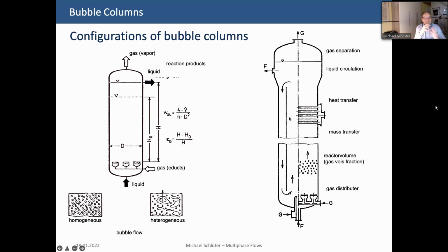So this is why often it's necessary to do laboratory experiments or even pilot plant experiments, which is much more effective and reliable, and then to adapt the correlations, and with the adapted correlations to pray that they will be applicable as well for a larger scale. This is how it works.